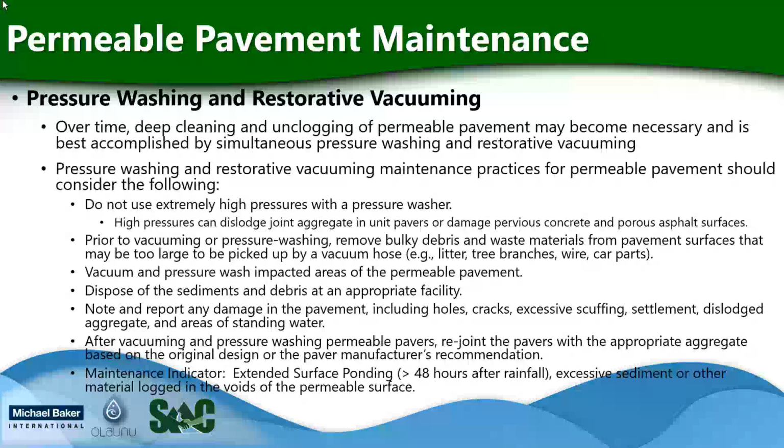Your maintenance indicator is extended surface ponding of greater than 48 hours after rainfall, excessive sediment, or other material lodged in the voids of the permeable surface.